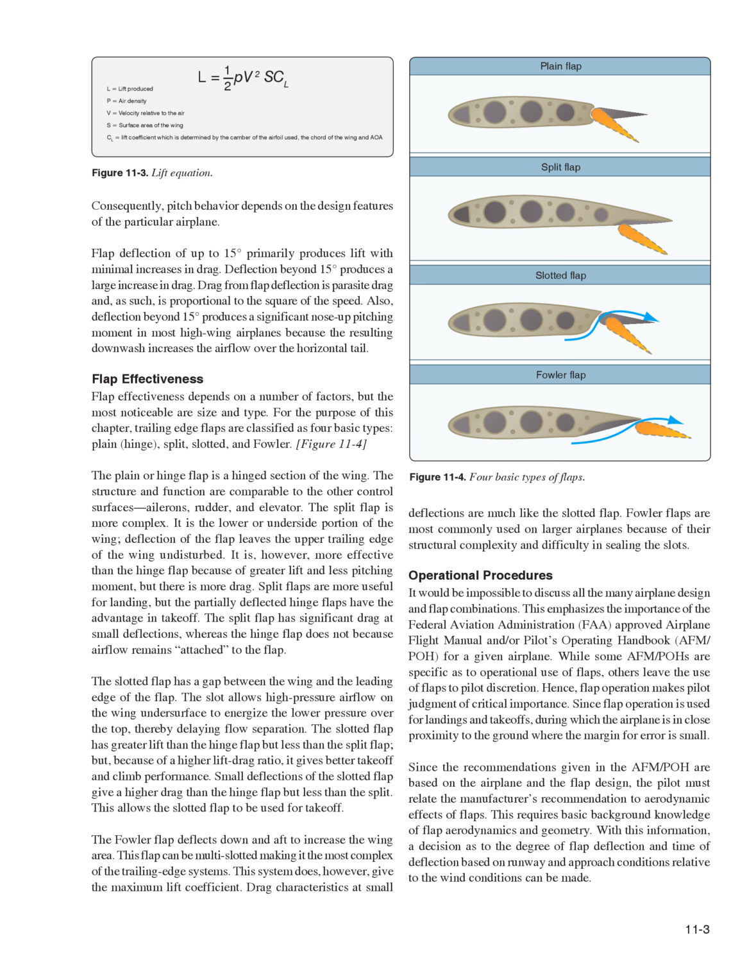Operational procedures: it would be impossible to discuss all the many airplane design and flap combinations. This emphasizes the importance of the Federal Aviation Administration (FAA) approved Airplane Flight Manual and/or Pilot's Operating Handbook (AFM/POH) for a given airplane. While some AFM/POHs are specific as to operational use of flaps, others leave the use of flaps to pilot discretion. Hence, flap operation makes pilot judgment of critical importance.